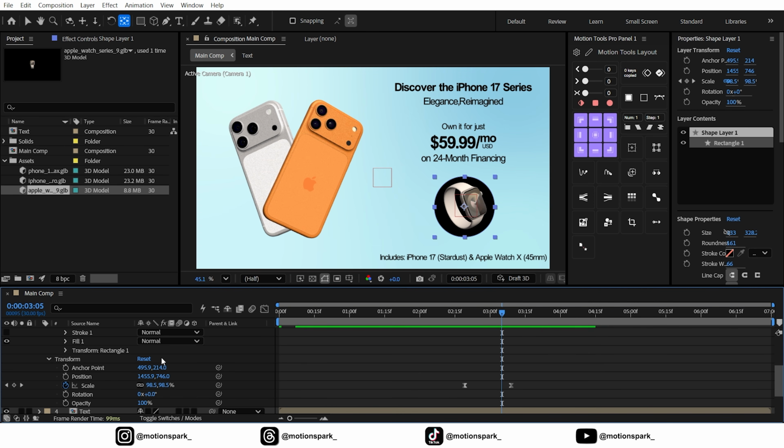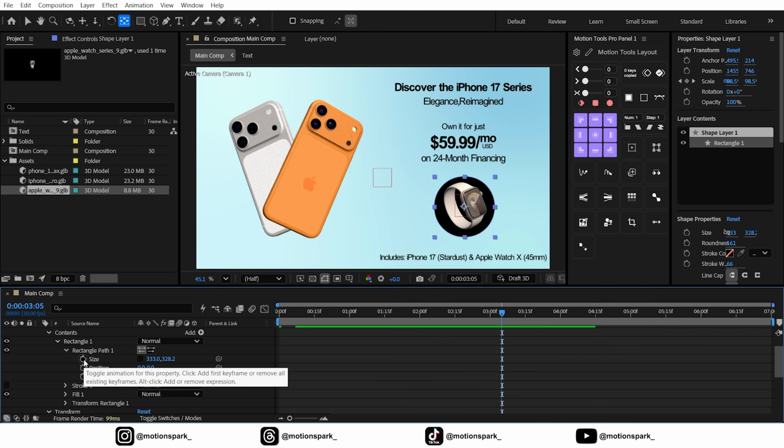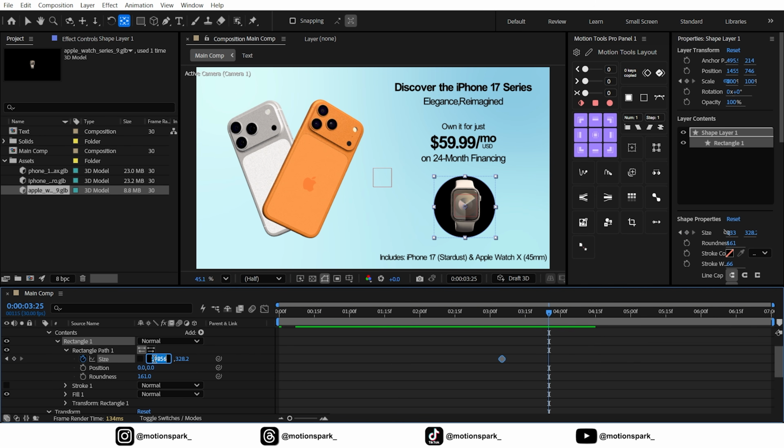Great. Now let's go back to the first size keyframe on our shape layer and add a new keyframe there. Move 20 frames forward on the timeline, increase the size value, and bring it back to its original state. To match this transition, let's jump back to the very first keyframe, and this time, add a keyframe to the roundness property. Next, let's head to the final keyframe of the animation and restore this setting to its original value as well. This will make our shape morph smoothly from a perfect circle into a rounded rectangle.